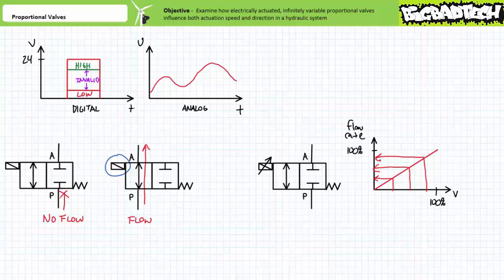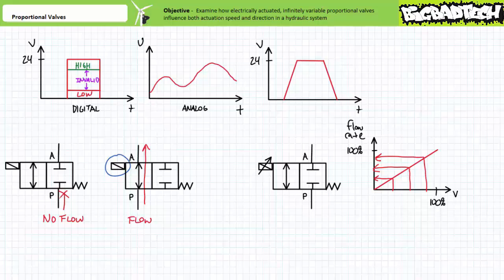While substantially more expensive than a regular flow control valve and directional control valve combination, a proportional valve offers additional functionality in a single package. In addition to simultaneously controlling actuator speed and direction, being analog in nature, the pressure shock associated with a traditional fully closed or fully open directional control valve can be mitigated, in that applied voltage can be smoothly ramped up over time, thereby slowly opening the valve and suppressing the shock. This ramping event controls the acceleration and deceleration of the applied load, as we'll learn in a moment.